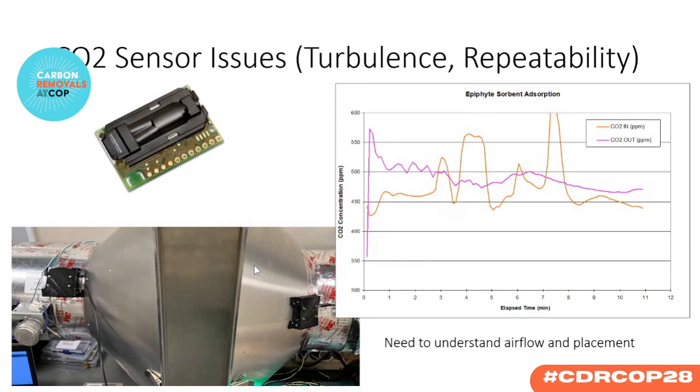The other thing that I think contributes, and it may not be contributing to the variability you're seeing, but it does contribute to the overall baseline, is the calibration of CO2 sensors. CO2 sensors are hard to calibrate, and they require a lot of time and effort that frankly we didn't put in. We have a very basic calibration procedure to get us a relative level, because what we were most interested in was the difference between in and out. But a better procedure to calibrate these sensors would get us better and more accurate readings.